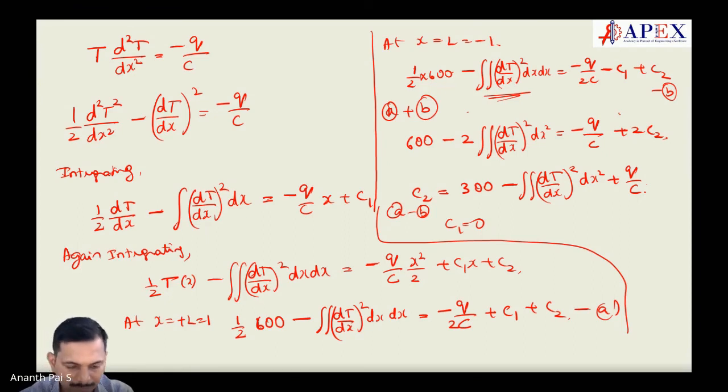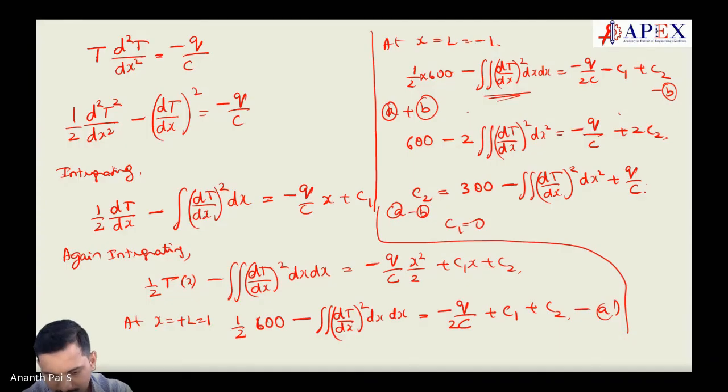Shailesh, enjoyed? Sir, I think you have derived one equation, the heat conduction equation in 3 dimensions. If you would have derived the same equation for 1 dimension, we would have got this easily, sir. I mean, like d square T by dx square is equal to minus q by k. That k came below because we have taken it as a constant from d by dx of k into d by dx of T. I hope you understood what I meant.